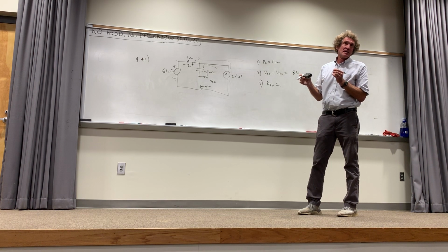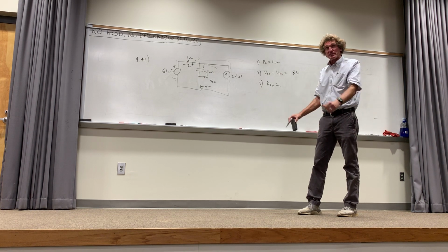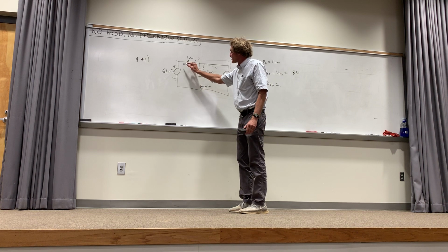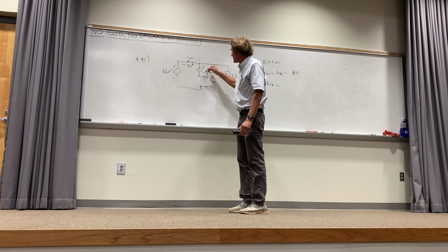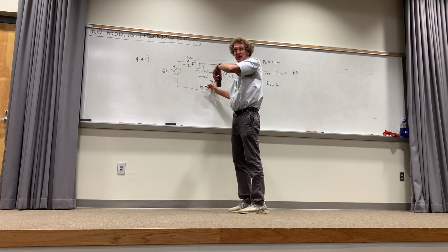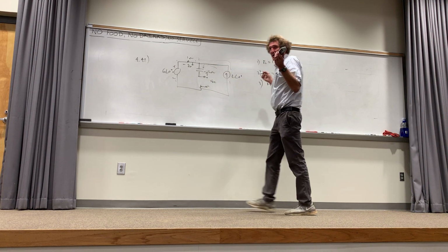I always seem to slip up the signs on the resistors. Well, here's what you can do if you went all the way around. You would say an increase of 6, an increase of 2, 0 volts, and then a decrease of VOC, all equals 0. VOC would go to the other side, it becomes positive. With me? That's all I'm doing.